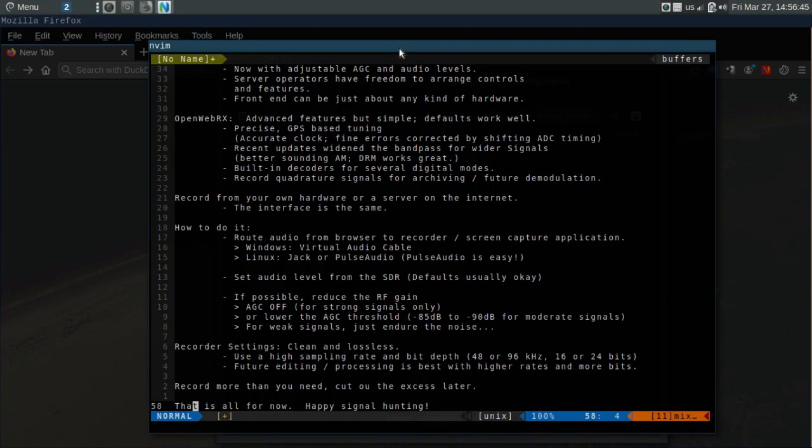If you have interference on an SDR, you can change your filter pass bands to eliminate interference on one side or the other. And if it's generally a weak station, then you don't have much choice. You'll have to narrow the filter pass band to get rid of noise.